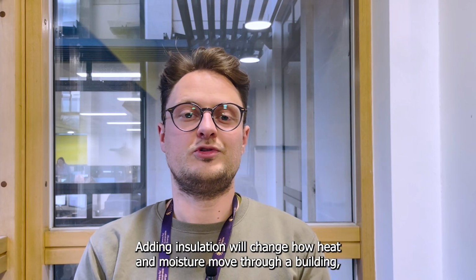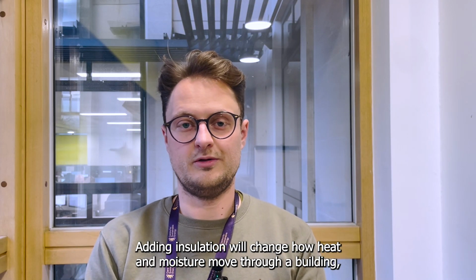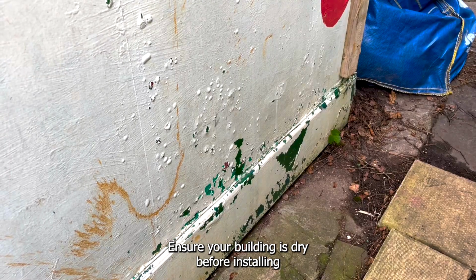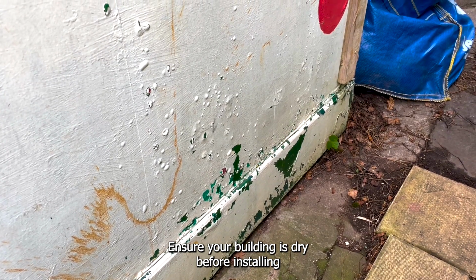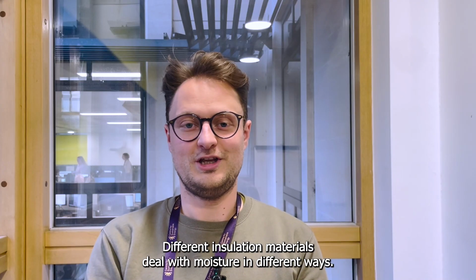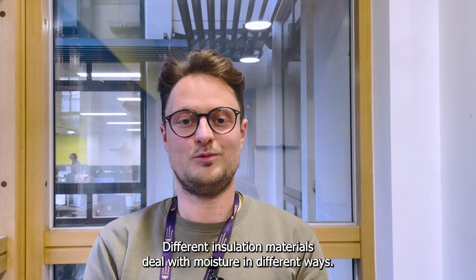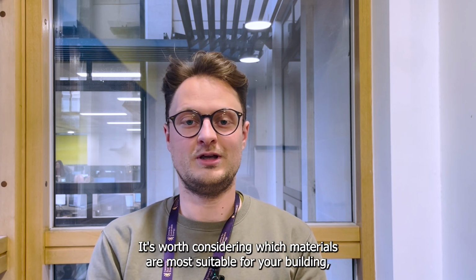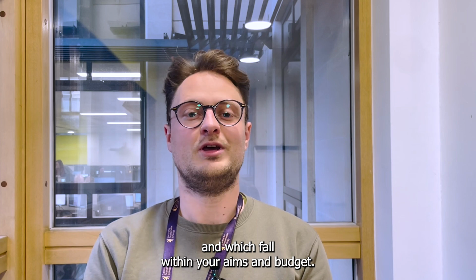Adding insulation will change how heat and moisture move through a building, so be aware that insulation may not always be appropriate. Ensure your building is dry before installing, and remember, maintenance is key. Different insulation materials deal with moisture in different ways. It's worth considering which materials are most suitable for your building and which fall within your aims and budget.